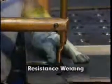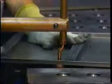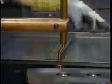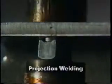Resistance welding processes produce coalescence of overlapping workpieces with heat generated by the resistance of the workpieces to the flow of electric welding current and the application of pressure. The three principal types of resistance welding are spot welding, seam welding, and projection welding.